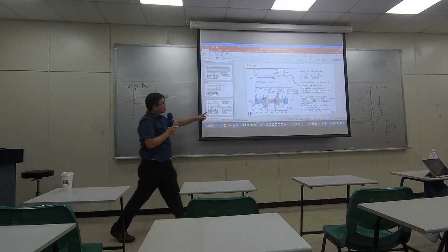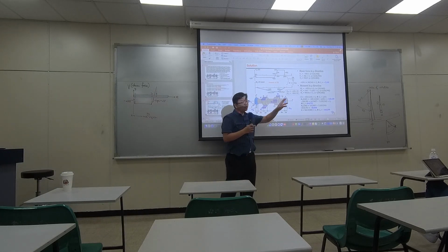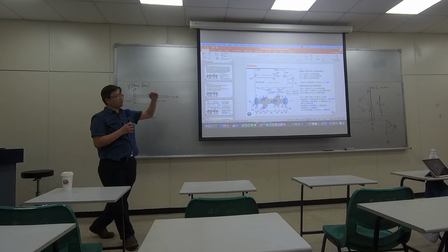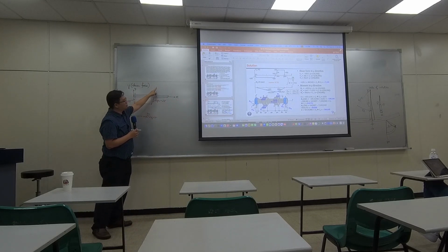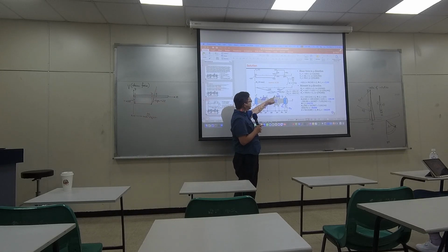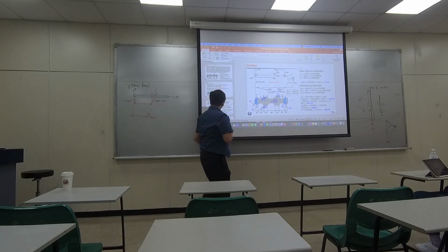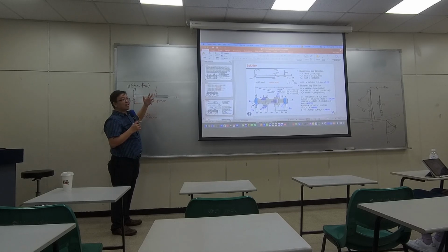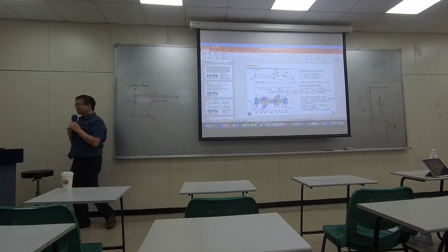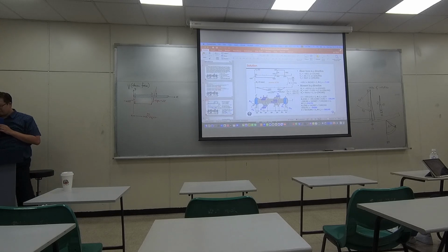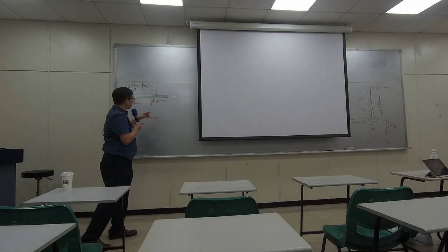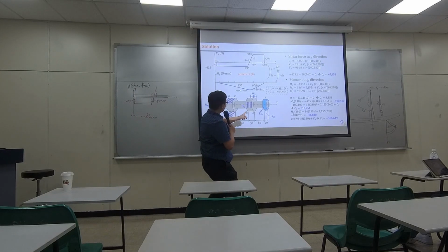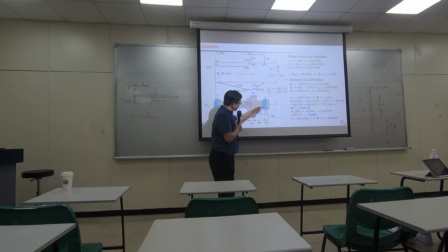right here, from D to E, the distributed load remains the same level. So we have a constant slope. If we have varying distributed load here, then this increment of your shear force will be nonlinear. That will be more complex. In my exam, I won't do that because you don't have time for that. Okay. But for you to know why we have this.